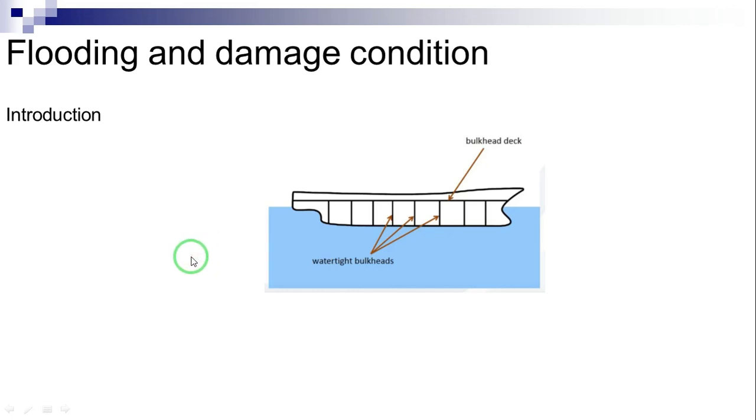Also, submerging part of the deck reduces the water plane area and can cause a substantial decrease of the metacentric radius. Flooding of non-adjacent compartments, for example, one in the forebody and the other in the afterbody, can produce negligible trim.